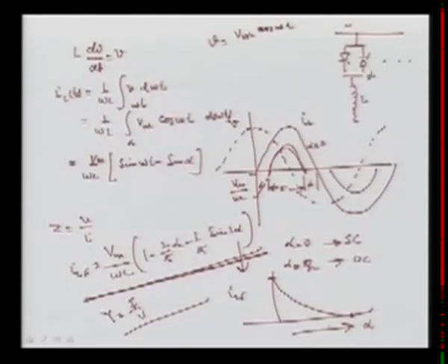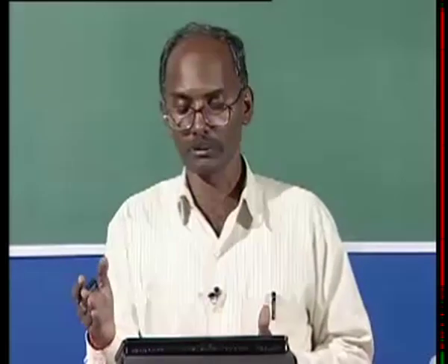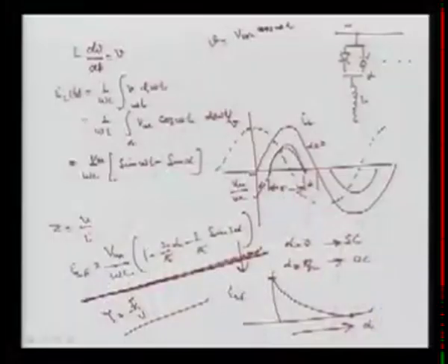Now what we are going to do in this one is look at a very important characteristic. We'll see that with the change of alpha and other components, because we are adding some capacitor, we will have different zones. There will be one portion where this X will be cancelling out with the other X, and then we'll have some resonance, or we can say margin, where we should skip from inductive operation to capacitive operation. Means in this STATCOM we are going to add here this capacitor.